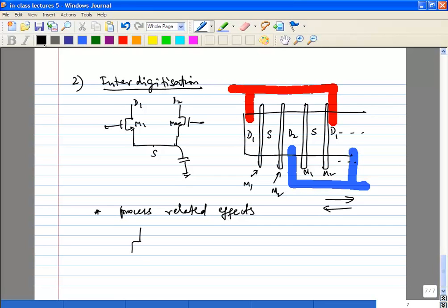Another case where you might want to have it is, let's say, a cascode. You have a common source-drain node here, and you would want to do the same thing. For example, if you have an LNA and any parasitic capacitance here, your VRF is here, IRF flows like this, and you want all of that current to flow here. So you want to minimize the parasitic capacitance at that node. You don't want to lose any signal through this path. So you definitely want to interdigitate and reduce the capacitance.